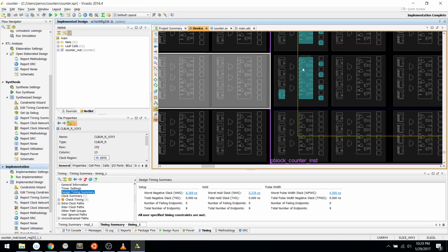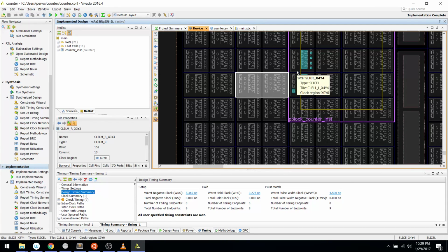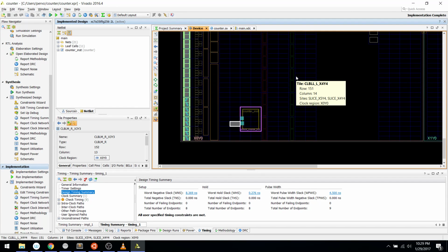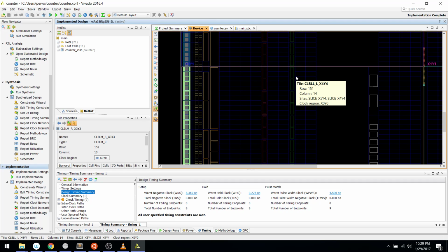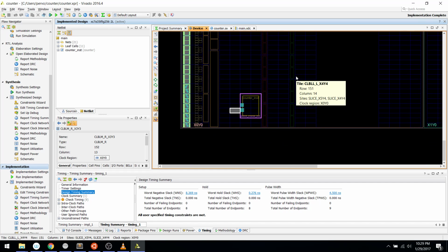But anyway, all right, so that's P-blocks. The P-block stuff is generally only something you want to do for big, chunky placement, like you're instantiating a big IP block and you want to say, hey, put it here near these pins. You don't want to use this for super fine-grained stuff, like I said, because it's too brittle, basically, with respect to changes, both with respect to the source code and also the device you're targeting.